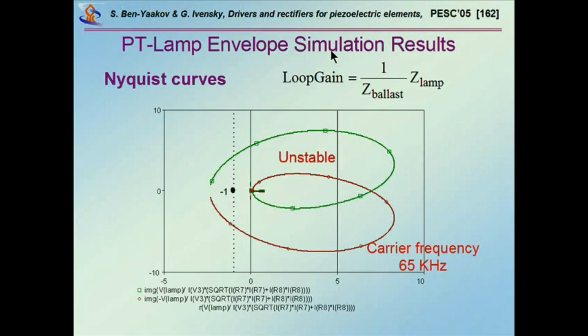It's not important. What is important is the incremental impedance for small changes, because you are running it at a given carrier. You are stabilizing everything around a given point, and the question is then, how will this system behave around this point? And it will behave differently for one carrier than another carrier, as I showed you.